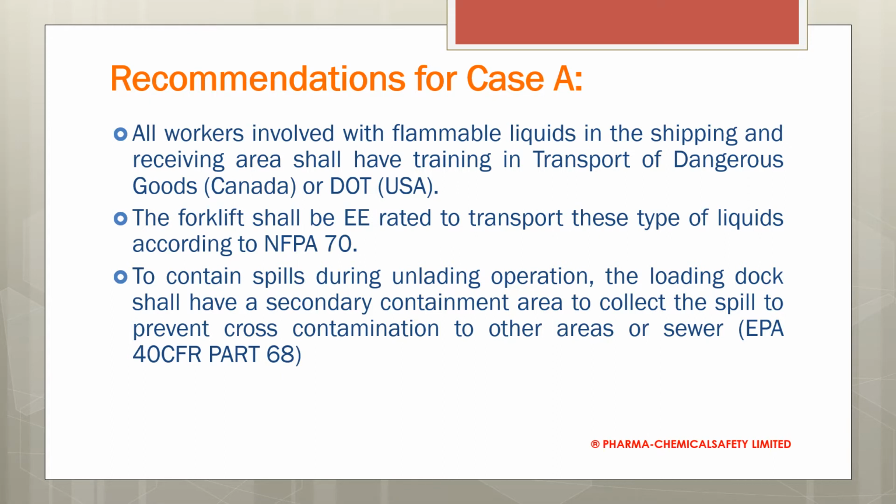To contain spills during the unloading operation, the loading dock shall have a secondary containment area to collect the spills, to prevent cross-contamination to other areas or sewers, according to EPA 40 CFR Part 68. And in Canada, the same with the regulation from the Minister of Environment.